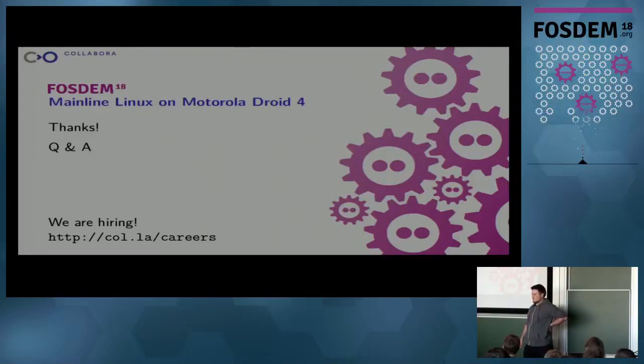It's connected via I2C. What the Android-based kernel does is that it takes the I2C interface and tells the second processor, here, this is the I2C interface, do what you want with it, I won't touch it. So in the mainline kernel, we have not really touched the second processor, so I can just use the I2C channel and talk to the chips myself. The problem is that I have to enable them first, and I have to know how to enable them. For the flashlight chip, we managed to find out how to enable it. For the camera chips, we did not yet find out. So if we scan the bus, we won't find the chips.